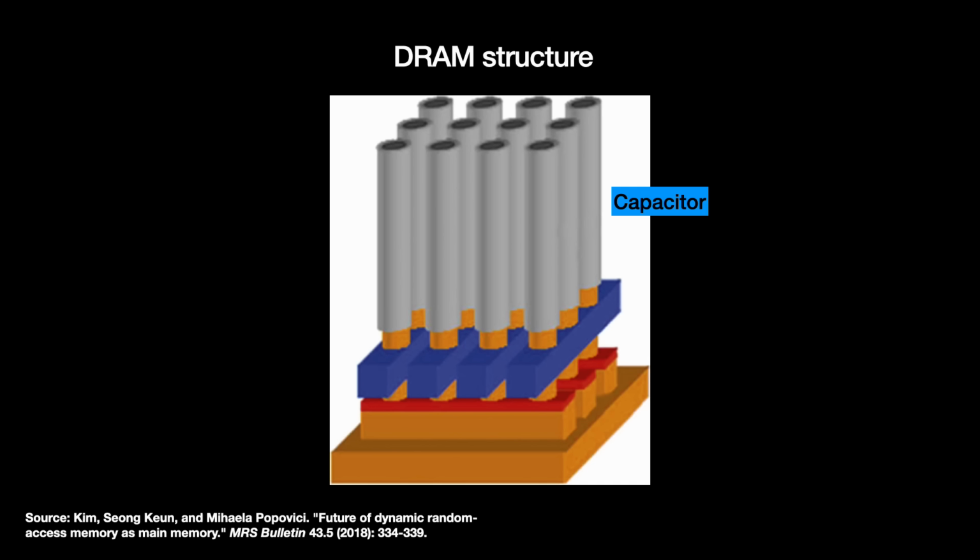DRAM cells are connected to two wires, a word line and a bit line. The word line connects to the cell's access transistor's gate, so it can turn them on or off. The bit line connects to the capacitor through the access transistor, and it is the path a charge can come in or out of the whole DRAM cell.